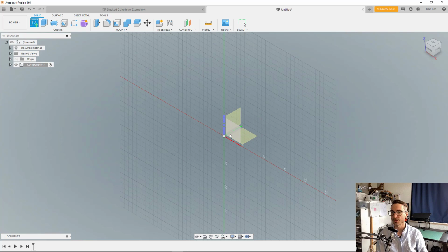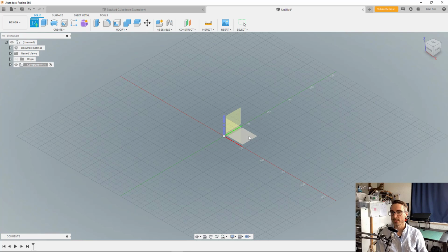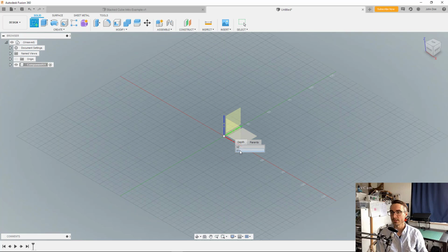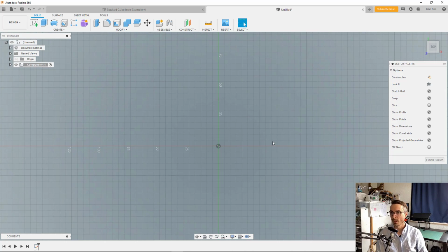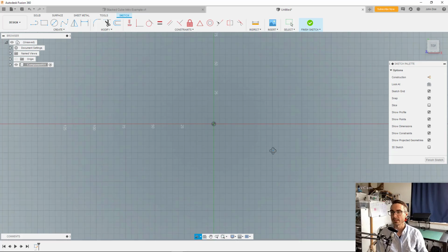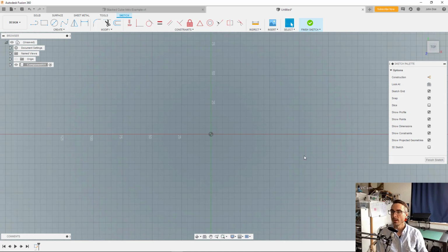but I also want to use this as a chance to show you another trick here. If that plane I wanted to select was inside an object or out of reach, I couldn't get my cursor onto it, you've got a trick here. Right now I'm on the ZX plane, this front square, but I see underneath is the XY plane. If I left click and just hold my mouse down for a second, I get this option to select a different type of geometry that's buried underneath. And so I can move my mouse up and down here to see which one it is. So there's the XY. I'll click on that. It automatically snaps to a straight down view for us, so that's convenient. If you accidentally orbit away from that, you can always use the cube to return to that view.